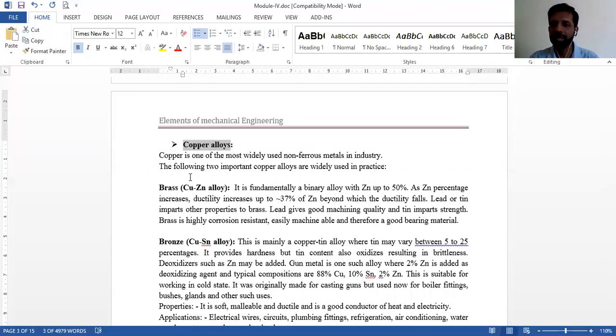If you look at any AC, or the pipes carrying the refrigerant in a refrigeration system, these pipes will be made of copper and not of any other material, because of its very good thermal conductivity and electrical conductivity. Majorly we use it in refrigeration and air conditioning systems because of its thermal conductivity, that is, it can absorb heat very quickly and give out that heat to the other system or to the atmosphere very quickly. So there is a very fast heat exchange when we use copper, and that is the reason why all these tubes are made of copper.